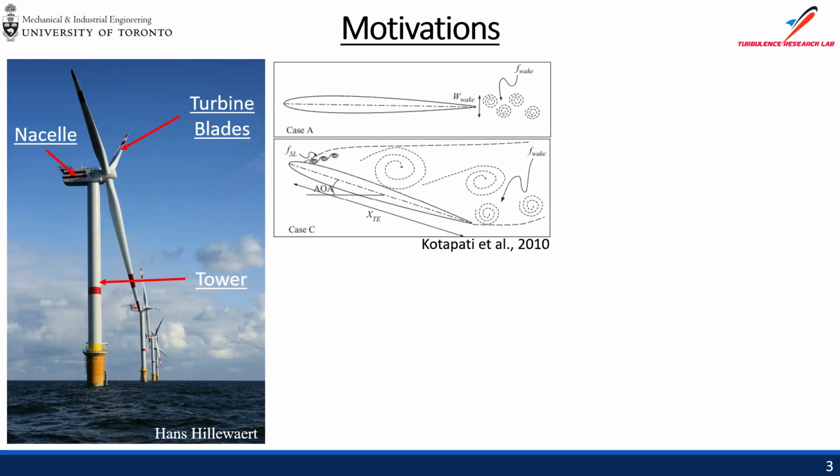Starting with the wind turbine blade, if you cut across it to create a 2D cross section, it actually resembles an airfoil, similar to what you expect on the wings of an airplane. And similar to the wings of an airplane, when you increase the angle of attack, or pitch upward, you generate more lift, but it also leads to stalling, which on a plane means you will not be able to take off. And on a wind turbine, you basically generate less electricity.